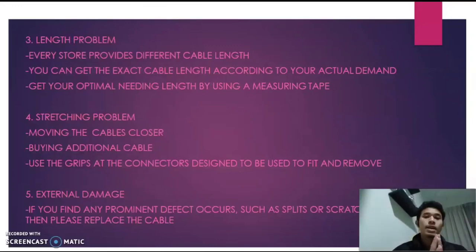As for the conclusion, fiber optic technology has been used in many fields of telecommunication, photonics, medicine, and engineering. This has attracted many researchers because of its performance, low loss, uninterrupted service, higher bandwidth, and high data carrying capabilities. Although fiber optics has many advantages, there are still some disadvantages associated with fiber optic technology. One of the disadvantages of fiber optics is that fibers are more expensive when compared to copper cables. Other than that, a highly skilled workforce is required for fiber optic installation.